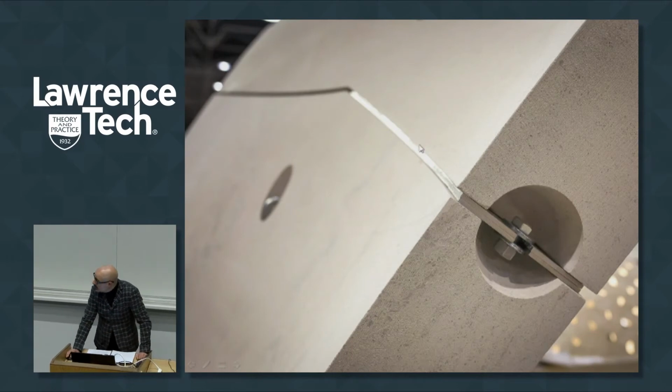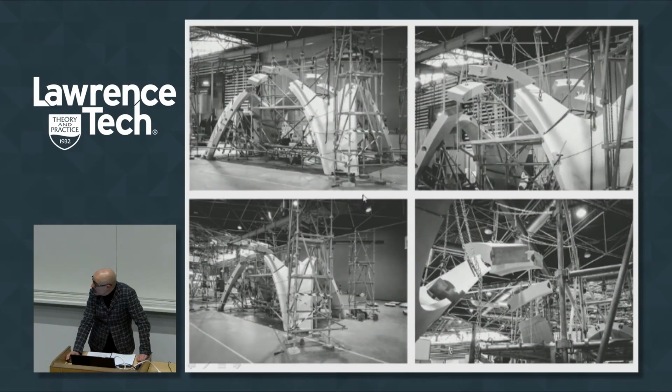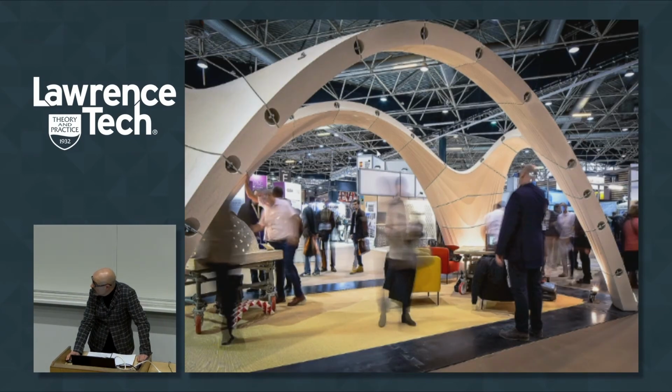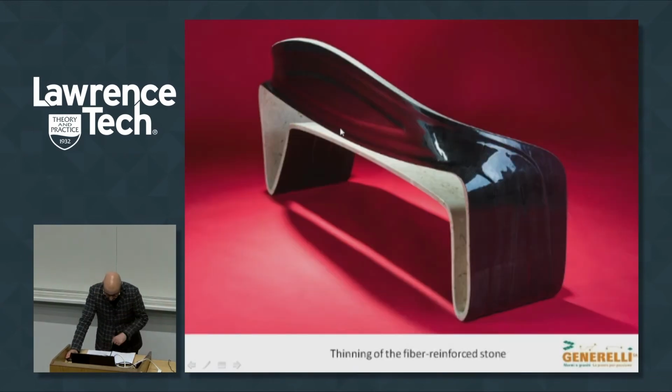pavilion, using this technique of pre-anchorage of the joint, and using this kind of metallic system just to fix during the mounting. So here you have some pictures during the assembly the day before the exposition, because during the exposition the pavilions are made in wood, in something very quick, never in stone. So we proved that also with the stone we can be very rapid during the construction.